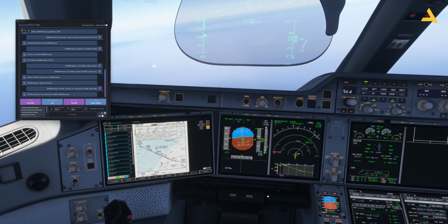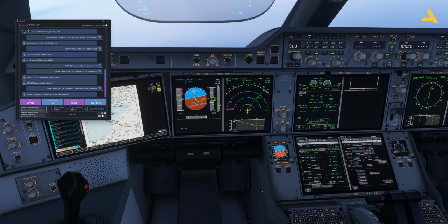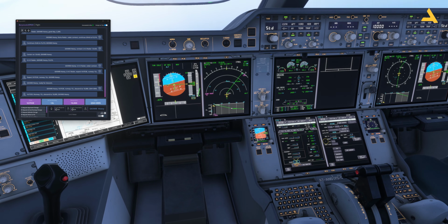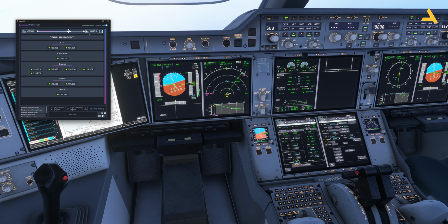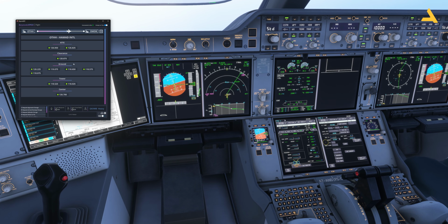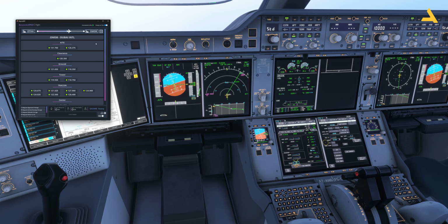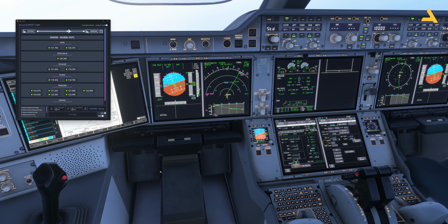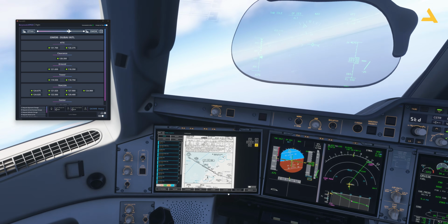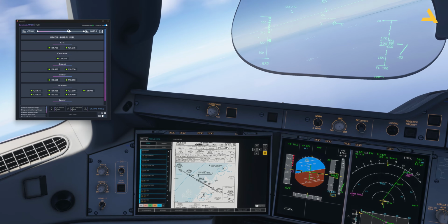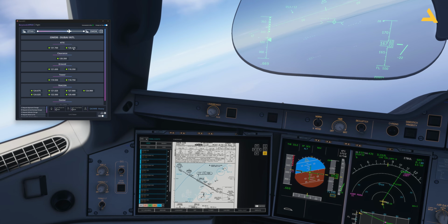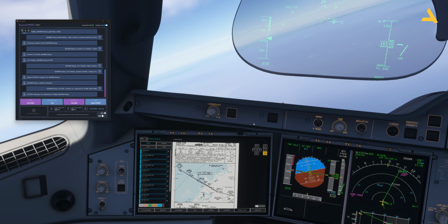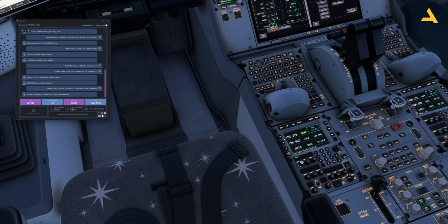And now let's enter the wind information. You can also tune into Dubai ATIS to get the weather information. Let's try doing this. If I go over here, right now you can see different frequencies are appearing for Hamad International Airport, but if I want to get it for the Dubai International Airport, I can just select this option, or you can also get it from the approach plate. So it's 126.275. I can just tune into this frequency.